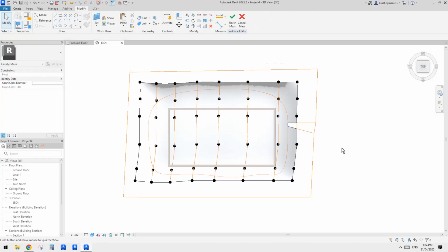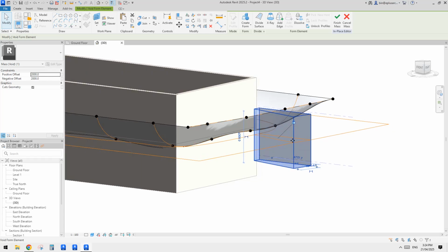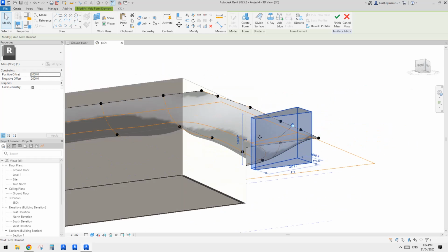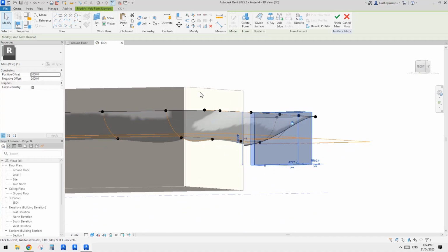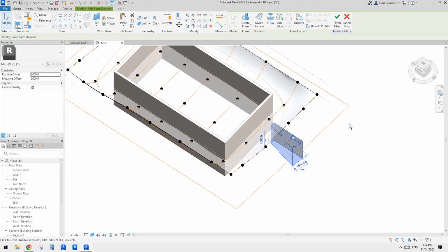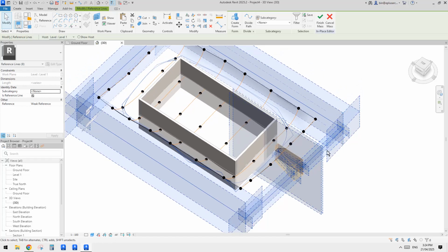So if I go to 3D view, you will see this is the void, right? By default it will only start from this level 1 and go up, and it might not be enough for that shape, so I put another number in the other direction. And then again, we need to move the cursor from here, so you can see, select the whole thing here. From here go down, oh actually no, go here and then go this way, back down, go that way.